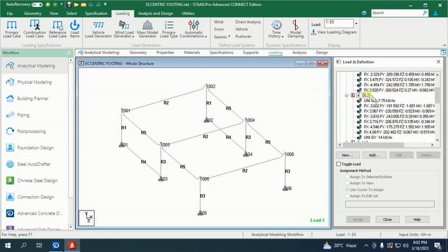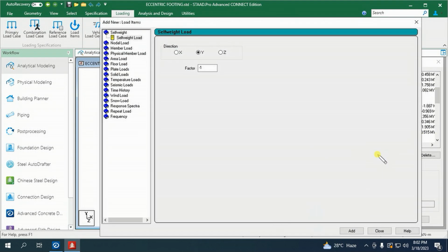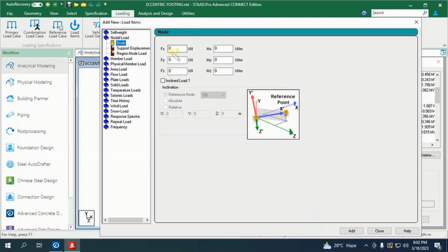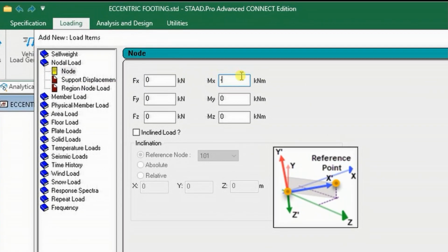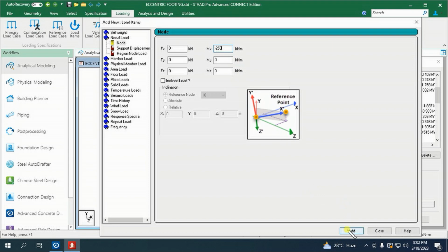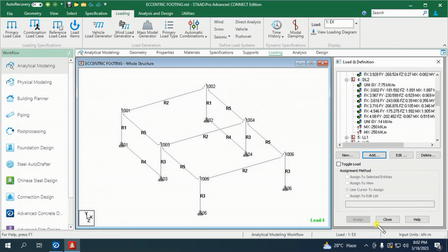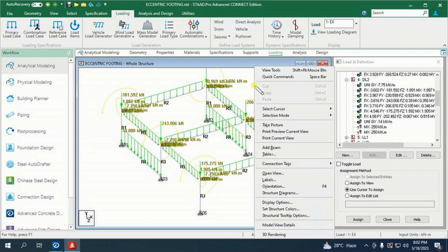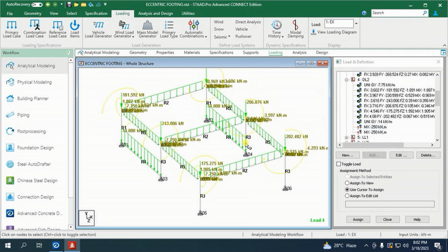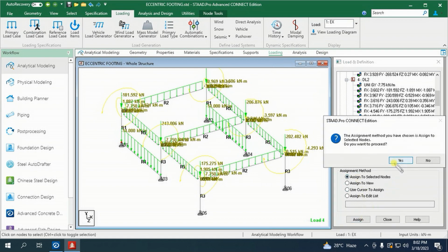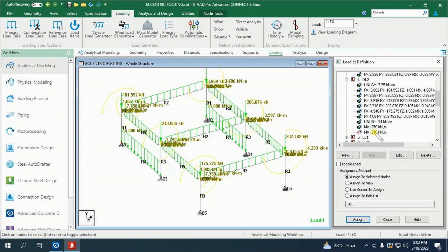We will initially assume a moment value of 250 kN-m on both columns. Upon application, the strap beams and grid beams will react, and if the size is inadequate, the beams will fail in the design. If the strap beams fail, there is no need to resize them to make them pass the design. Instead, gradually increase the column size until the strap beams are okay.